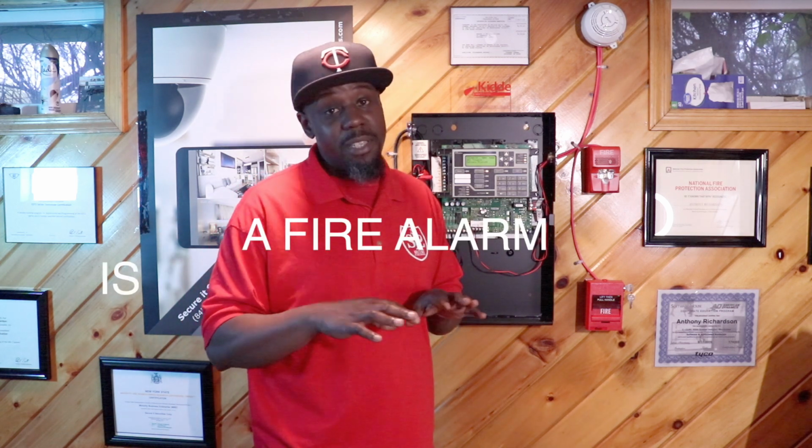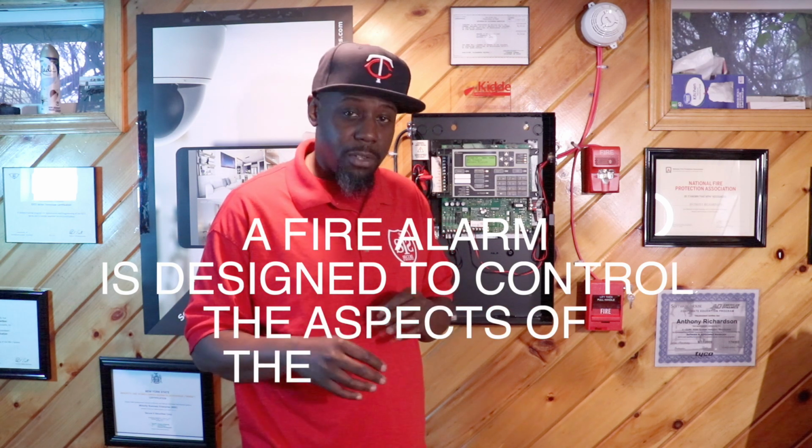Finally, we have what I call specialty type fire alarm systems. Now, not every fire alarm system is designed this way. For example, in high-rise buildings, a fire alarm is designed to control aspects of the building's environment. Say there's a fire on the 10th floor. The fire alarm will then activate on the 10th floor, on the floor above, which is the 11th, and on the floor below, which is the 9th. That alerts the occupants of those three floors that there's a fire in your area, or there's a fire above or below, and now I need to exit the building.